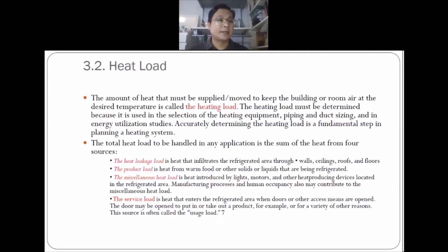Okay. And then the last one, the service load, is the heat that enters the refrigerator when the door or other access means are open. So the door may be opened to put in or take out the product, for example, or for a variety of other reasons.